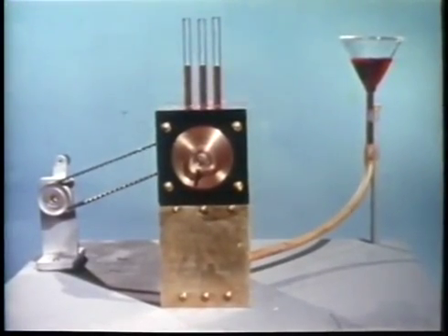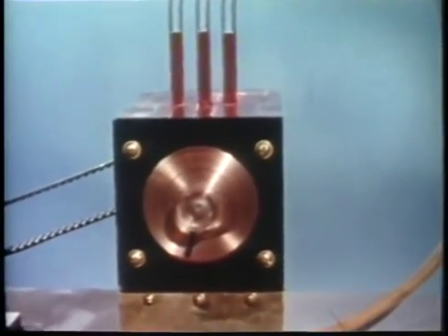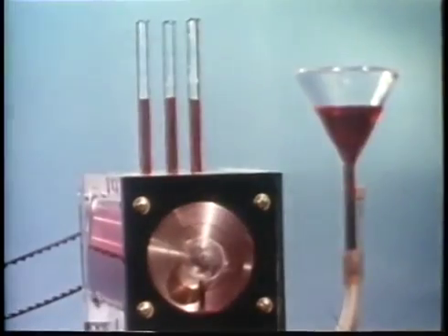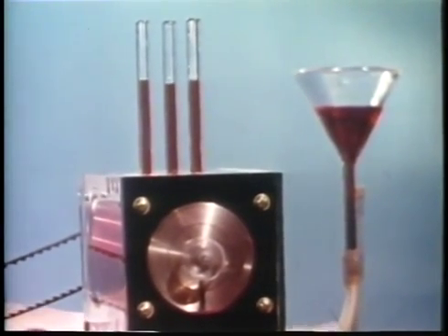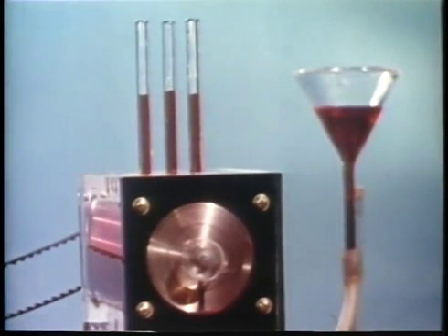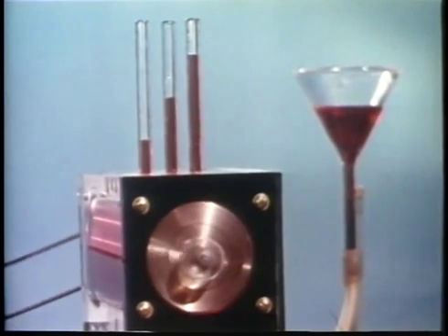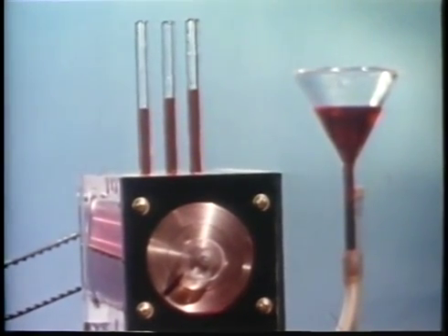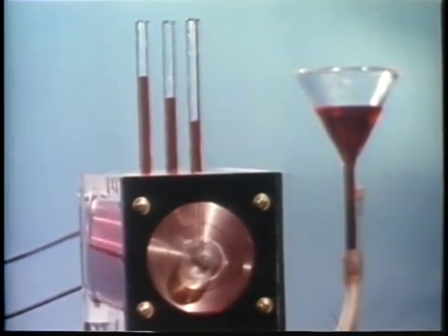The center manometer is located at the narrowest part, with the other 2 equally distant from it. Here the fluid is water and the manometers are open to the atmosphere. In the converging channel, the pressure rises above atmospheric and then falls below it an equal amount on the diverging side. Reversing the direction of rotation reverses the stresses and the pressure distribution.